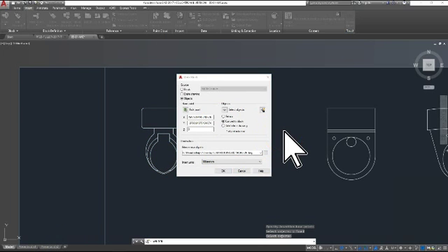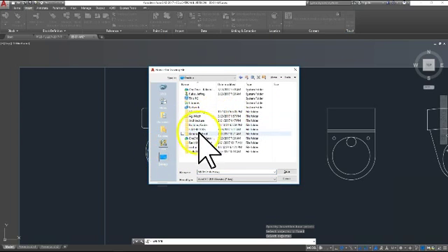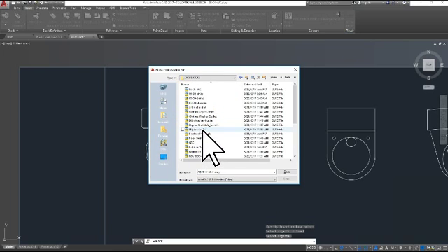Next, mouse down to the Destination cell and you'll see the file name and path bar. To the far right of the file name and path bar, click on the small square button to bring up your File Explorer. From here, select the folder that you would like the CAD block to be stored in. Hopefully, you have set up a folder for storing your CAD blocks. In the file name box, type in the desired name for the new block and click Save.